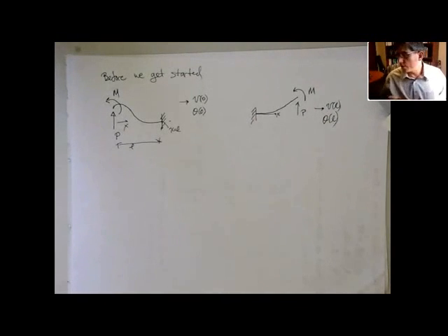So you can go through and integrate, get the bending moments and then integrate those twice, divide by EI, and get the deflection, and the first derivative gives you the slope. But since I talked about it in class, let me talk about this book. This is another way of doing it. I really recommend this book. I think it's an excellent reference for most engineers.